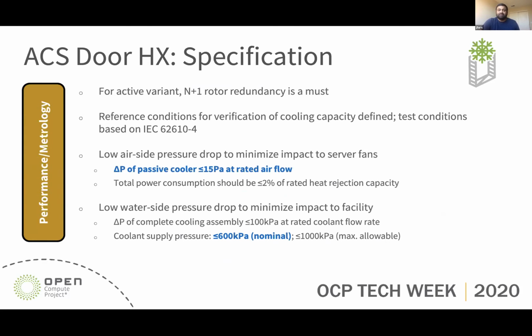If you have an active door heat exchanger, there's a minimum rotor redundancy that's a must. And with regards to the impact, not only to the rack and also the facility side, there are certain requirements depending on whether we're talking about a passive or an active door heat exchanger variant.